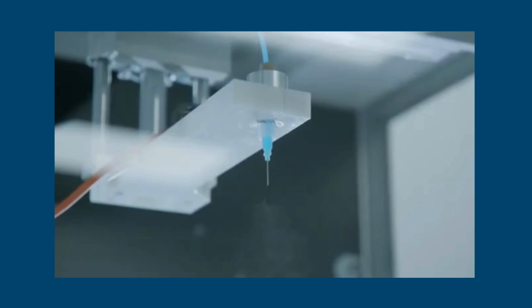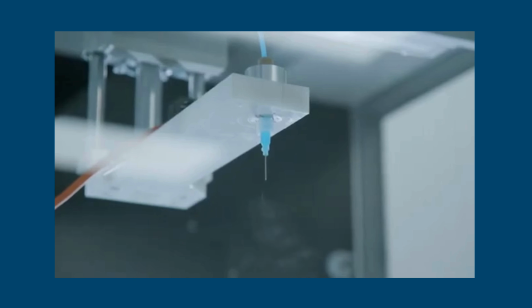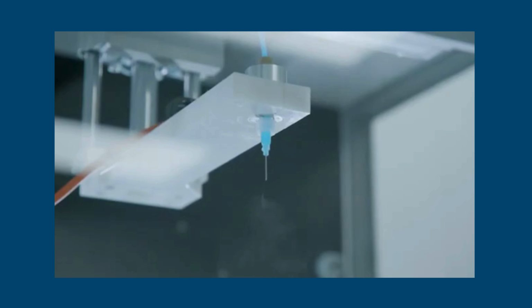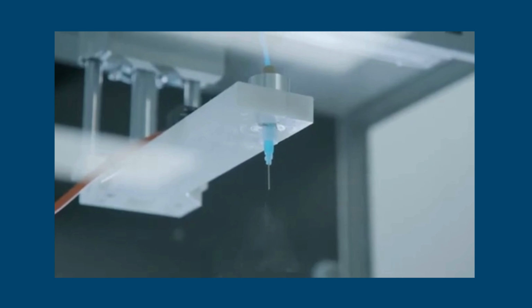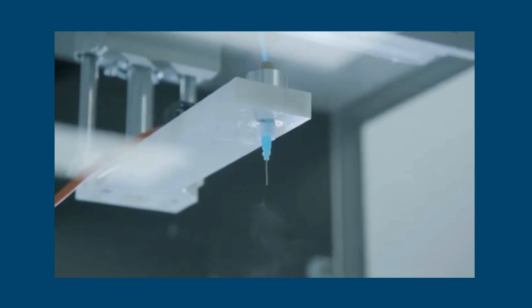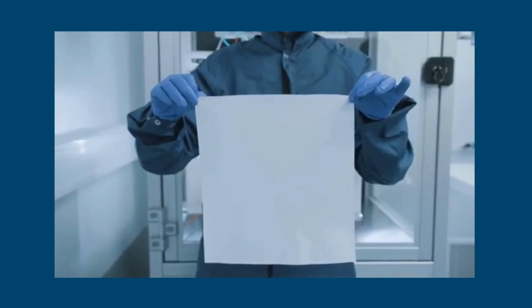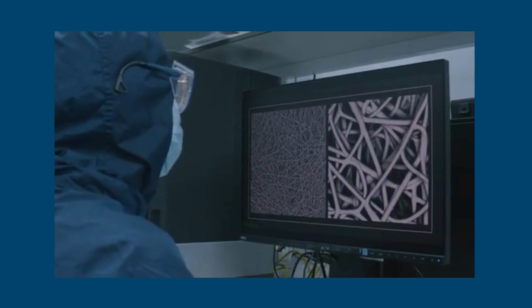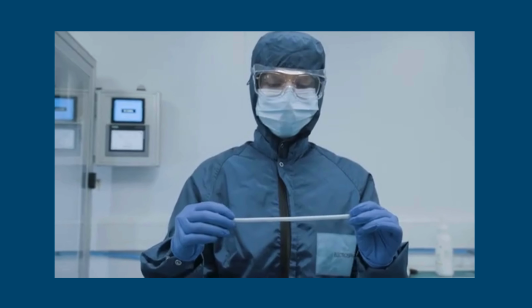networks. When the polymer is poorly soluble, such as polypropylene (PP), polyethylene (PE), and polyvinyl chloride (PVC), or requires a toxic solvent, melt electrospinning, a technique to produce fibers by using polymer melts, can be adopted instead of solution electrospinning, offering a promising supplemental method for producing fiber-based materials. In this process, a polymer solution or melt is subjected to a strong electric field, resulting in the formation of ultrafine fibers that accumulate into a porous membrane.